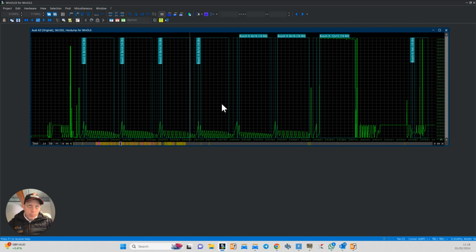So with WinOLS, you're dropped in the deep end a little bit. I mean, this is the basic view of an ECU. There's actually more going on in the background of actual computer programming. I don't know if people have done much computer programming, but say this map here, it's a driver's wish map. I know that just by how it looks. But that map would be linked to a bunch of other maps. So you might have torque, smoke, and all that kind of stuff.